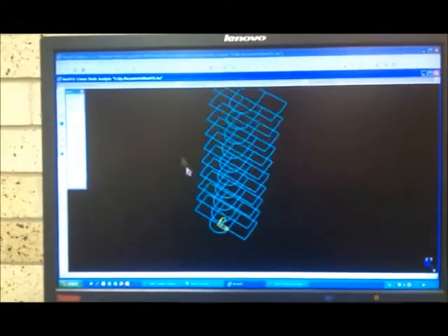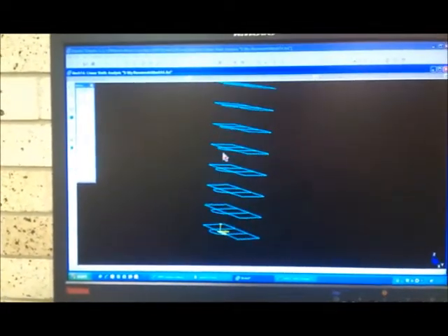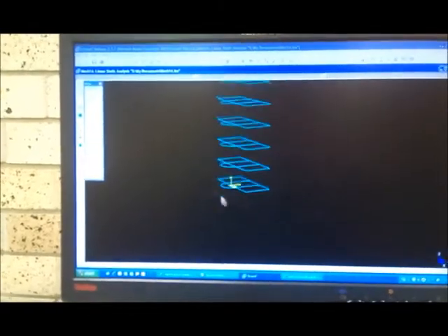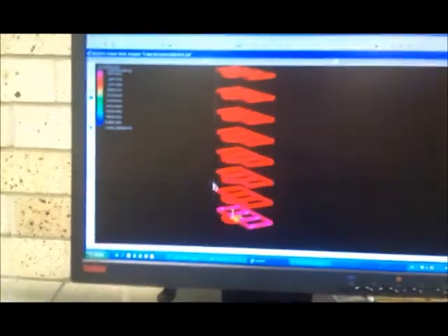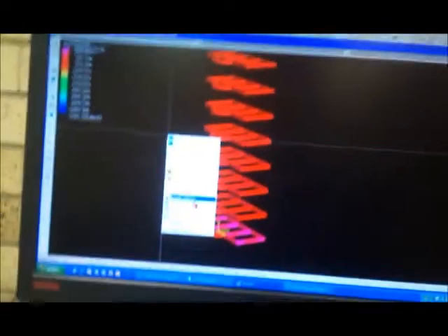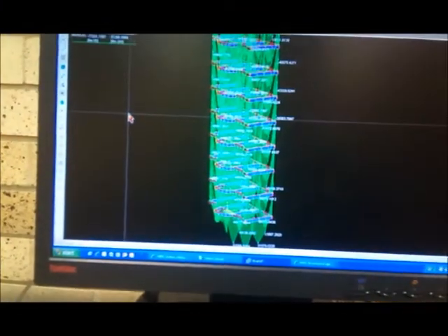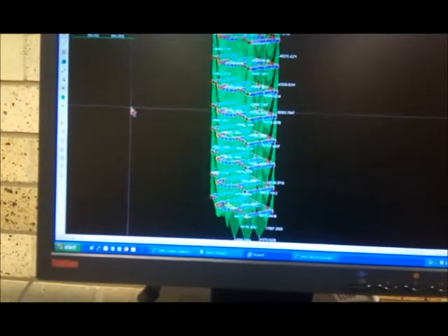Now what we should be looking at in the beams is what? Are we interested in axial forces? We are interested in bending moment. So right mouse click, result settings. Now I'll go to diagram, bending moment, and I'll put the bending moment. Now when you see it like this, you can't see anything. Right mouse click, result setting, and I'll reduce the size of the diagram. I'll reduce it a bit more. So good.